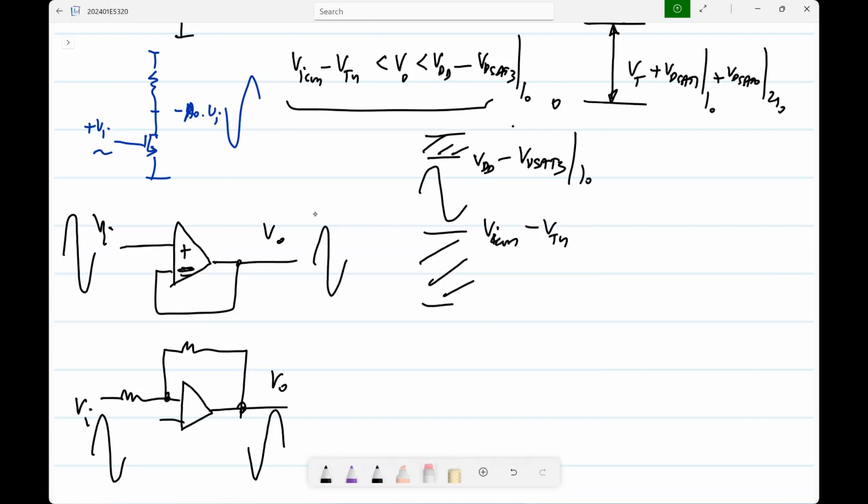So this is where it comes in. In this circuit, whatever signal you apply has to respect both the common mode swing limit and the output swing limit. In this case, the common mode is swinging. So the actual signal that you can apply could be limited by either the common mode swing limit or the output swing limit. You have to calculate and see.